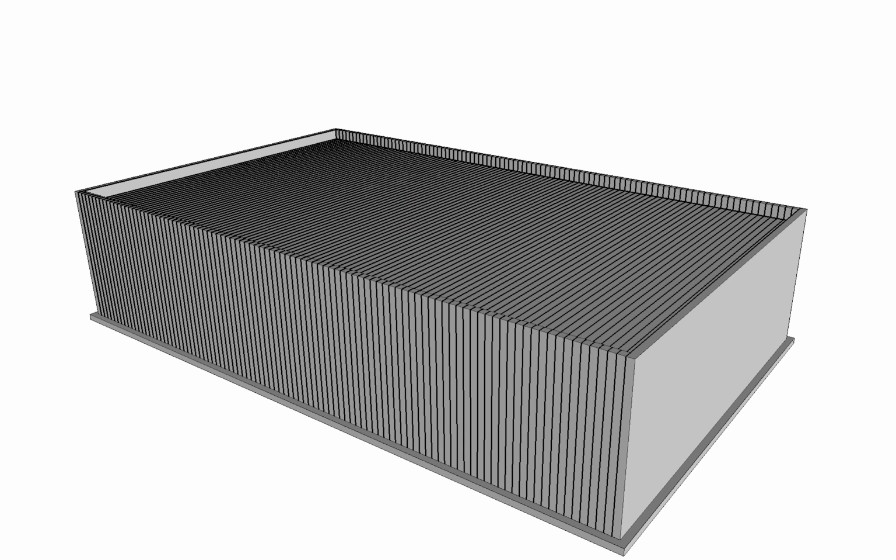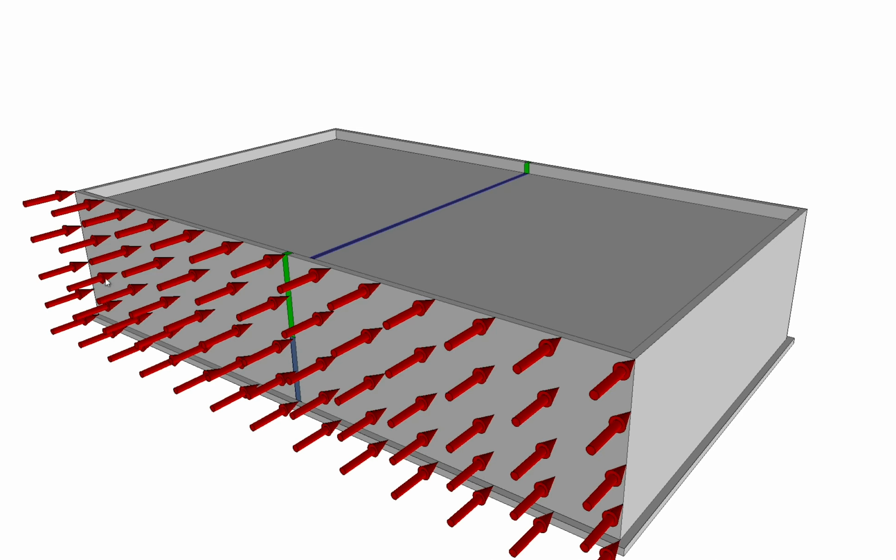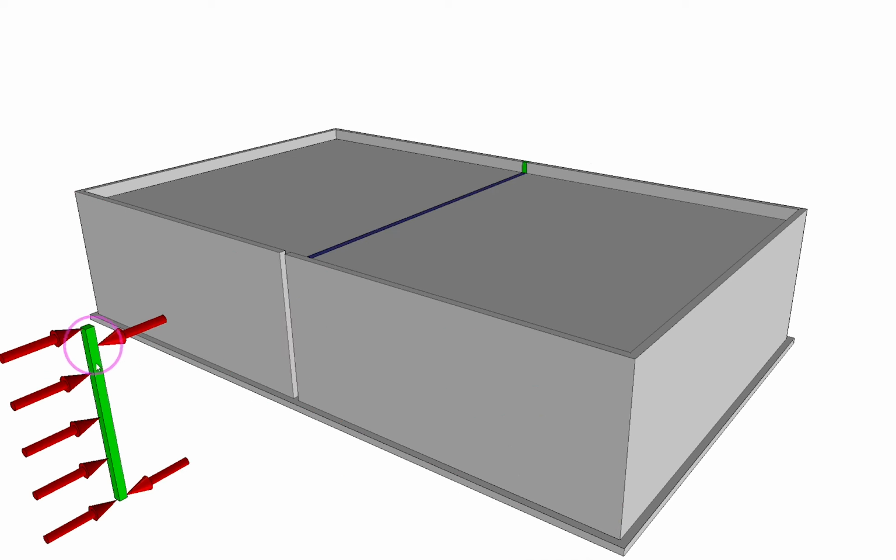So in the case of wind load, we would have the entire surface being pressured by that wind. Now this is going to vary as we go in height. I'm just showing these all the same. And there's our 1 foot segment there. So we will extract that 1 foot, and here's the wall.